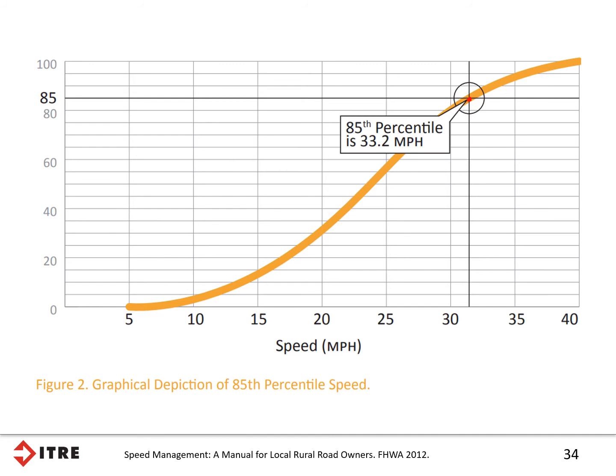But the Federal Highway Administration has clarified that speed limits are not required to be set based on the 85th percentile or other operating speeds. A review of practices and safety evidence for setting and enforcing speed limits on all types of roads noted that the practice of setting speed limits at the 85th percentile or some other related operating speed measure relies on the assumption that most drivers are capable of judging the speed at which they can safely travel, which may not be the case.